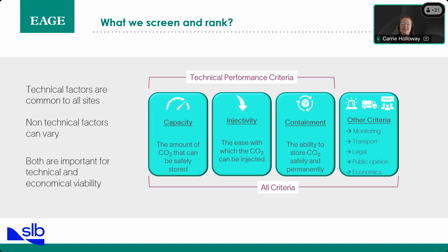In terms of injectivity, we're looking at how easy it will be to actually inject that CO2, how many kilotons per year can we actually inject per well. And this is going to be related to the connected pore space, the pressure conditions, the permeability of our reservoir, and also relies on us optimizing our injection strategy, so the placement of wells and the number of wells.